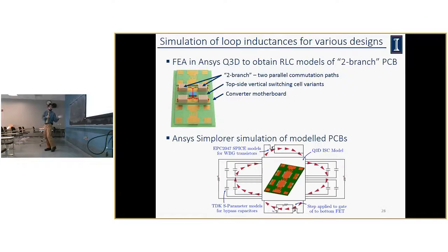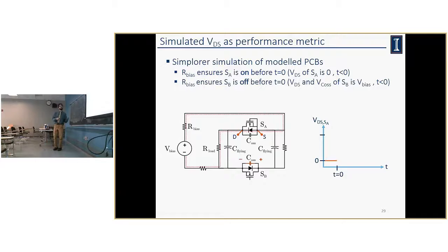So to simplify what this design is actually doing, we created an effective circuit that has a bias voltage, represented as the voltage normally across the flying capacitor, as well as a bias resistance. In this case, the bias resistance allows the top switch to be normally on unless we commutate the bottom switch. So we'll be driving this SB to actually trigger this transient. This ensures also that the COSS of the bottom switch is going to be charged while SB is not conducting.